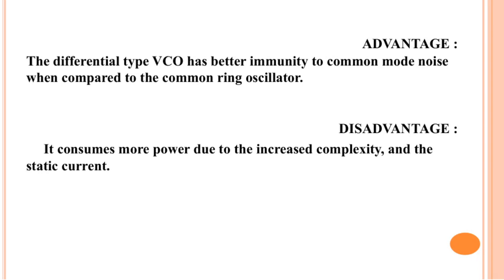Here, we're looking at the advantages and disadvantages of the differential-type voltage-controlled oscillator, or VCO. One key advantage is its improved immunity to common mode noise, which makes it more reliable in noisy environments compared to a common ring oscillator. However, this comes with a trade-off. The differential VCO consumes more power because of its increased complexity and the static current it requires. So while it performs better in terms of noise rejection, it demands greater power consumption.